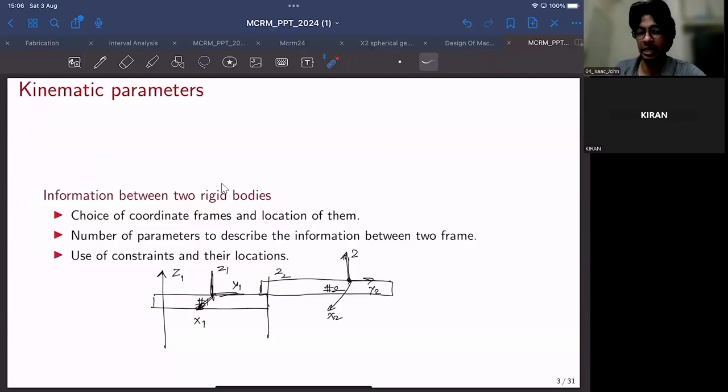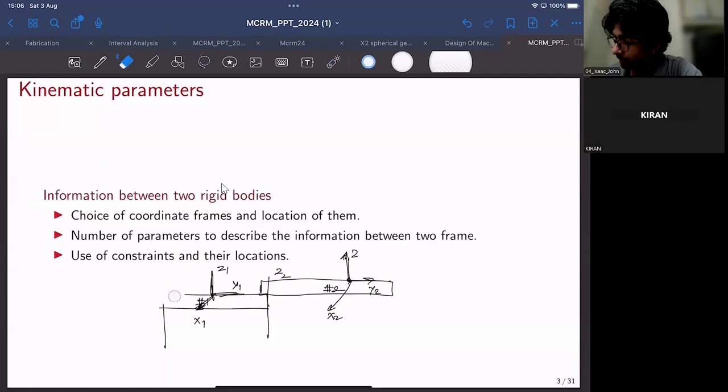So all these kinematic relations, the positions, the orientations, how the constraints can be propagated from the base all the way to the end effector, or how the forces can be transmitted along the robot manipulator, all these things can be facilitated using the frames of reference that are attached onto the robot manipulator.